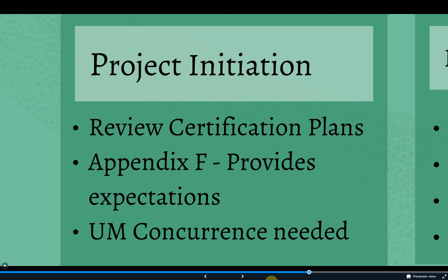In Revision C of the Procedures Manual, Appendix F was updated to address certification plan expectations. Certification plans that you see in the future should be similar in format to what is given in Appendix F, with only minor variations due to project complexity, safety aspects, etc. Items expected for consistency that were added to the outline include a list of page effectivity, project introduction, listing certification guidance material, listing data submitted to show compliance that includes the master drawing list, compliance data, installation documentation, and FAA submittals, and AD research.